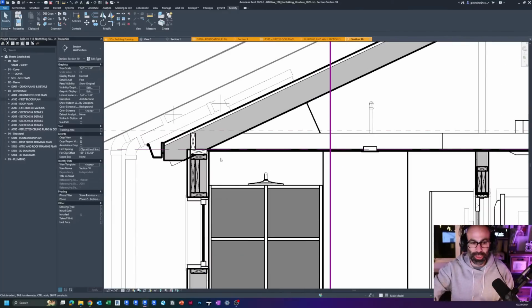So essentially, I'm doing two different things. I'm making it so that I have a better understanding of the design of this project. Once you put the headers in, even the sills can be helpful too, because if you put a double top plate or something, maybe you start to see what's happening with the dimension there. But I'm also making my sections, and I don't have to worry about using detail items. So sills, probably not a huge value add as far as design, maybe not even for the GC side of being able to look at the length and so on. But damn, is it nice to be able to cut a section anywhere you want along this wall section. And you have a sill plate, you have a top plate, you have your headers, everything in there.